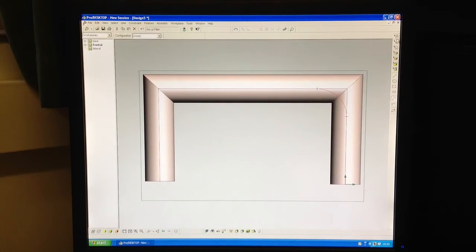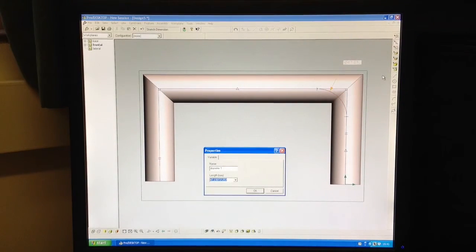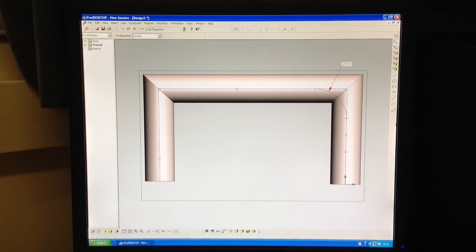The best way to do this, if I fix that line by selecting it and clamping it down, doing the same with this line here, clamping it, I can now add a dimension or sketch a dimension onto that radius tool. Now I'll need to select it, so if I try to click it now, it's basically going to try and sketch a dimension between that line and the one I'm touching. So I need to select that radius, sketch the dimension from that radius, and at the moment it's got a diameter of 47. I'll change that to 50, and it has done that.